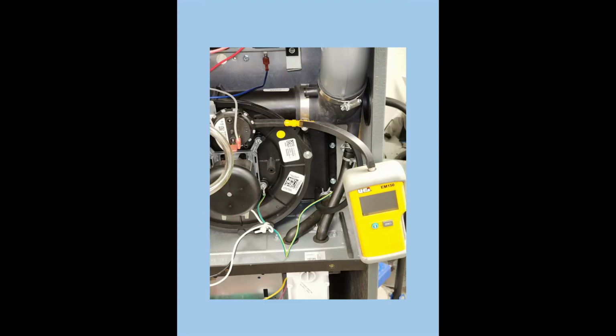Same here. We're into the front cover pressure switch now, and we just put the tube in there. We're breaking it, putting our T. We've got our manometer here, another piece of tube running down to our front cover, where we would measure that vacuum pressure.